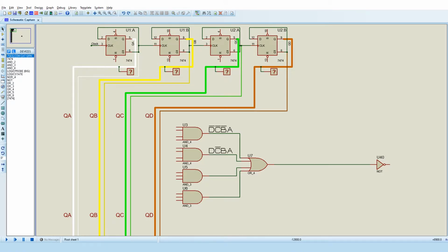And these are the 4 binary expressions that we worked out earlier for the value of not A. So we just wire them up. The output from the OR will be not segment A, because we worked it out to be not A, equals all that.